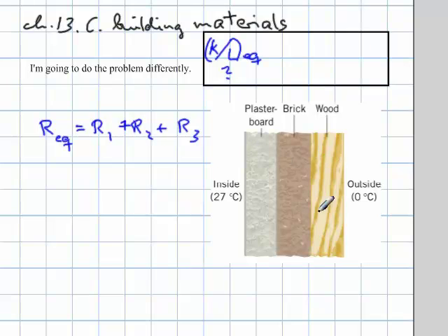The same thing happens with thermal conductivity. After all, heat being conducted sounds almost the same as electricity being conducted. In fact, the equations are the same. So the heat encounters this resistance, and this resistance, the heat flow that is, and therefore we would add the resistances. Now, the way it turns out is that the resistance is what I'm looking at here, but what's given in all these equations here, or in this particular equation, is the conductivity, which of course is the reciprocal of the resistances.